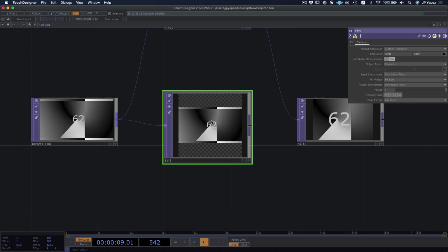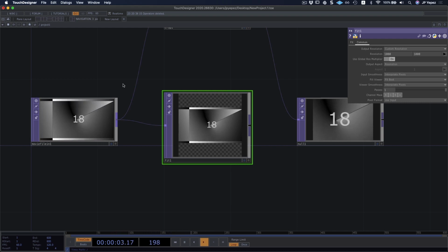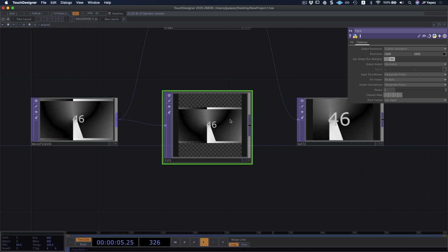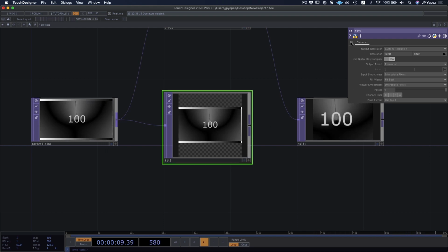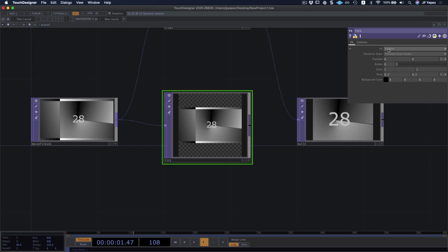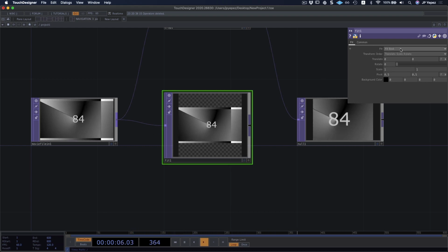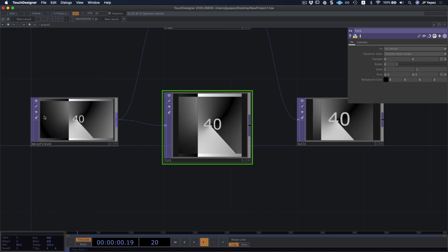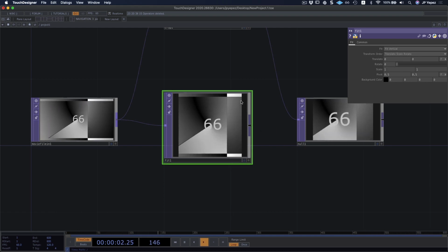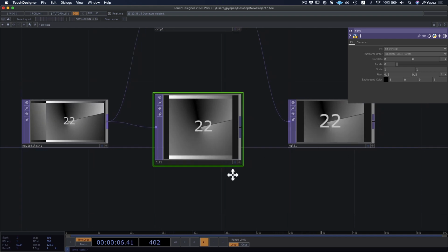And now here's the problem. This image happens to be longer, have more of a width than it does height. So it doesn't quite work for this resolution. I can select how it fits by doing fit best. It happens to show all the image, but maybe I don't want that. So I could select fit vertical, and it's cropping parts of it, it's cropping the sides of it, but at least it fills up the whole viewer.